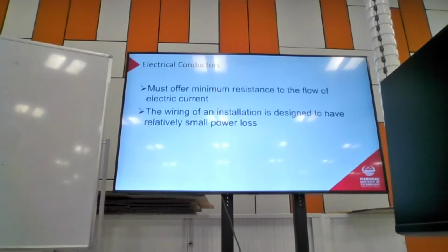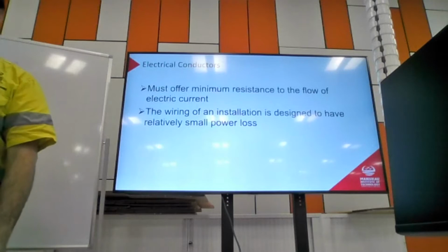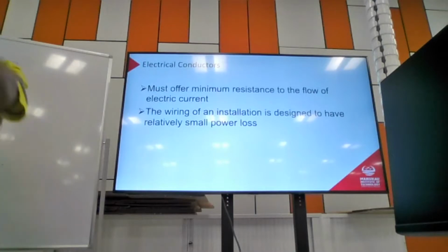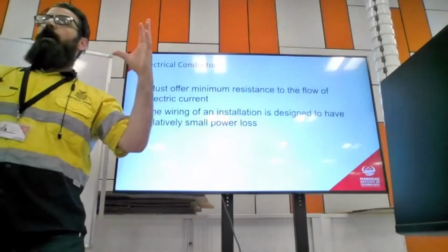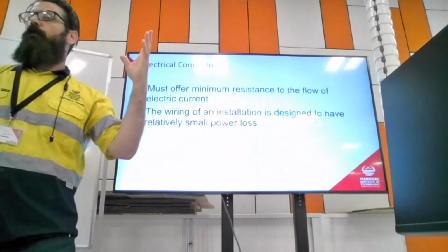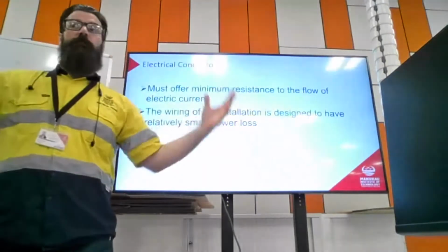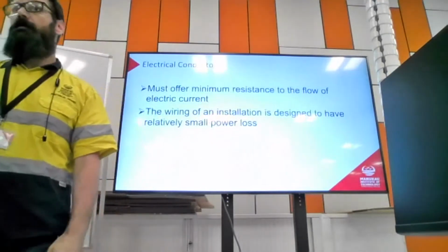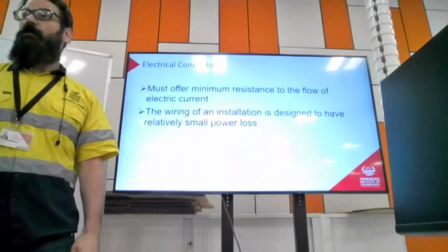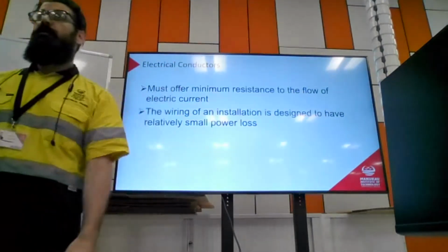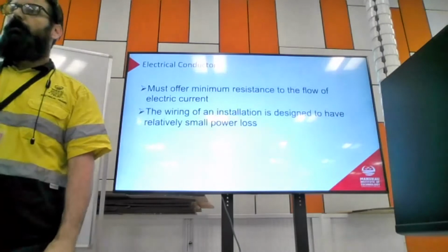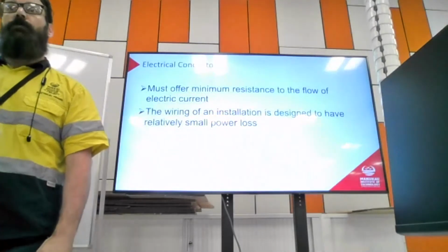What else might, maybe not in the case of a 20 watt cable, but what else could be an issue with power consumption in the cable itself? It's going to heat up, yeah, it's going to cause heat, and we don't want heat losses. So we can also see then that the greater the resistance, at any given current flow, the bigger the volt drop must be, right? And the bigger the volt drop is, then the more power I burn, that power is going to be consumed as heat. So what does that tell us about the relationship between heat produced and the resistance of the cable?